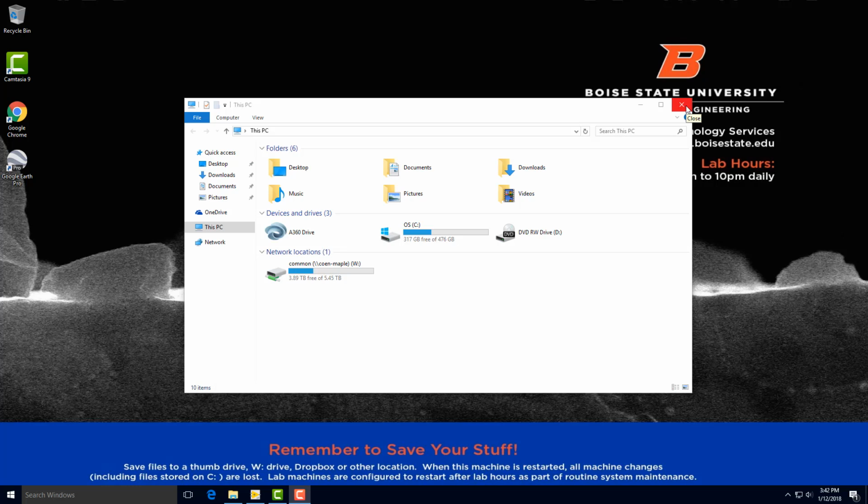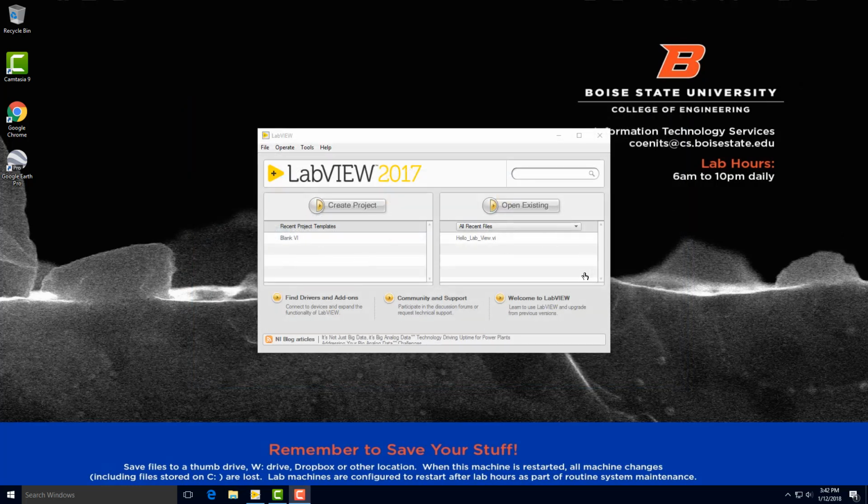So as we learned in the first class, we are first going to connect our data acquisition card into the USB port. And here today with me, I have an accelerometer, a triple axis accelerometer, together with a shaker. The shaker is going to be used to generate signals, and then we are going to use the accelerometer to record them. You're not seeing the mechanical setup, but that's something that you're going to see in your lab.